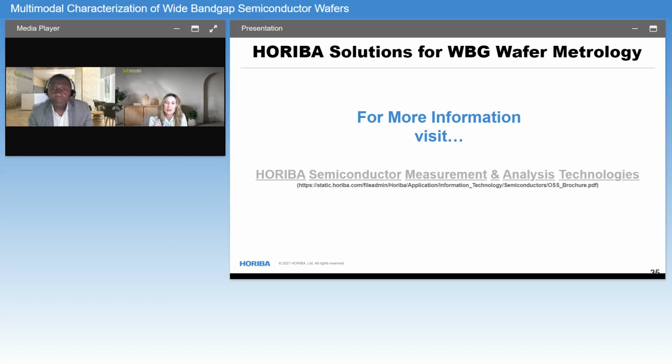Thank you. And Francis, how fast are typical measurements for Raman and PL? It depends on the objective. I've mentioned two things: uniformity and defects. For uniformity, depending on what you're measuring, often we don't need very high resolution. I'll throw some numbers out there. We're able to map, for example, a 1 millimeter grid on a 2-inch wafer in something like 2 minutes. Going up to 300 millimeters, it can easily be 15 or 20 minutes. But oftentimes there's a need to look at some feature with very, very high resolution, and depending on that area, it can be from a few minutes to several tens of minutes and even hours.